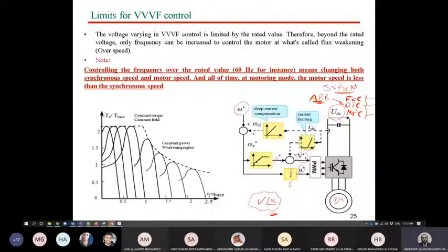It's one of the techniques used to control induction machine, and it's based on space vector or vector control of the machine. So finally, the decision will be a vector, and this vector can be translated as some pulses which will drive the inverter. This is what's called the variable speed drive. Inshallah, this will be the last topic in our course. What is the variable speed drive and how can we control it? This will be discussed in detail in the last few weeks, inshallah.